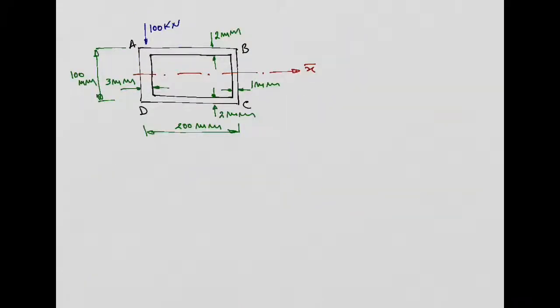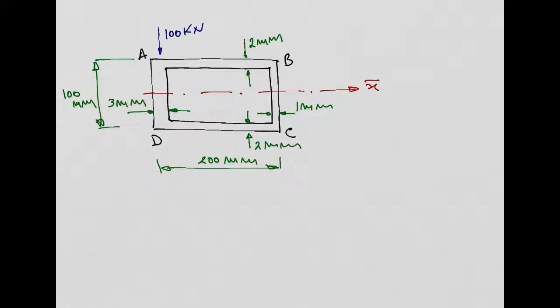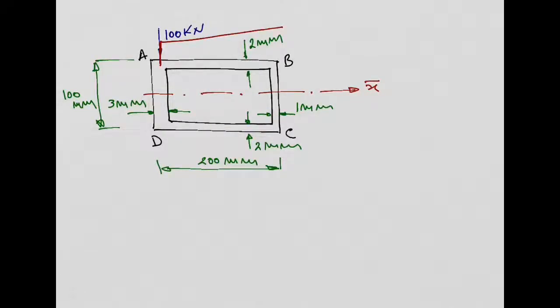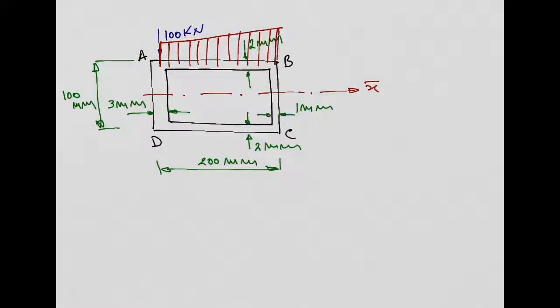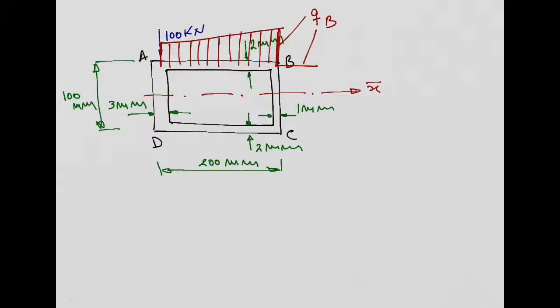So, what we can say is, if we start at point A with this initial shear flow, let's say this one, the shear flow will go from point A to point B linearly, okay? It will grow from point A to point B, and then it will arrive at point B. So this term here is going to be QB. So I'm going to say this is also going to be QB, because then I'm going to define a new variable starting at point B, this one, SB, and continue the analysis now from point B, all right?